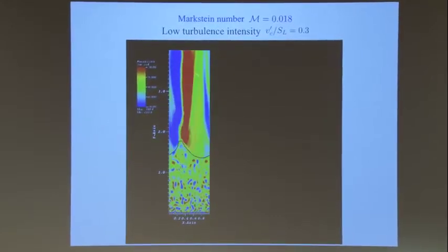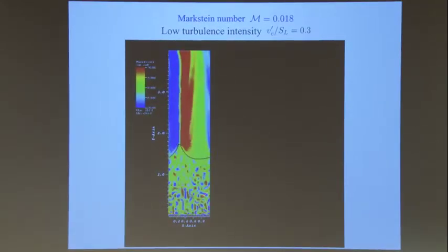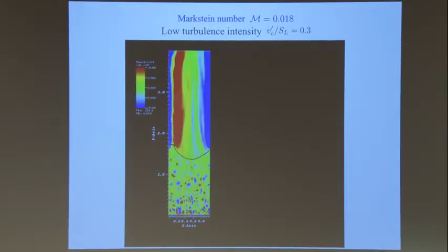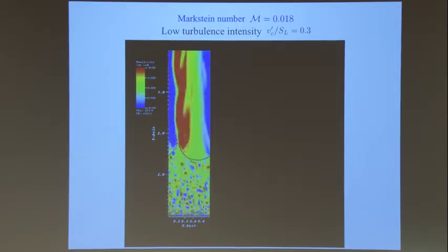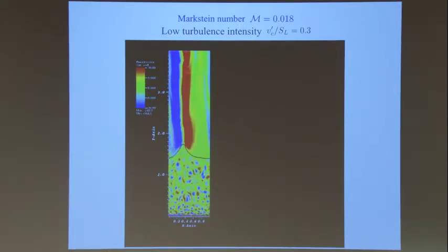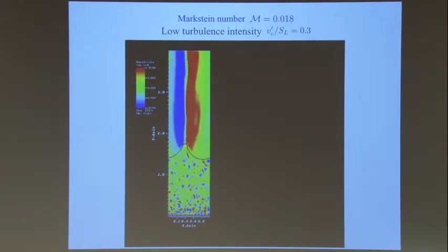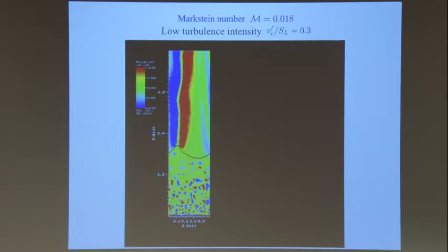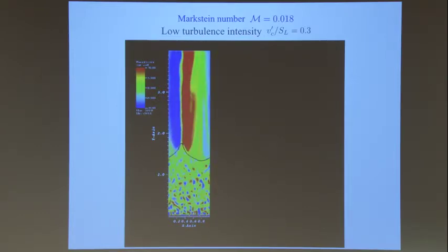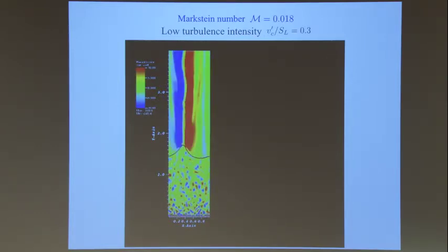Now you see the vorticity. By the way, these colors are vorticity, blue and red, different directions. And now you see clearly the vorticity in the burnt gas. Mostly the intense one comes from the peak, from this highly peaked structure that is created. Okay,